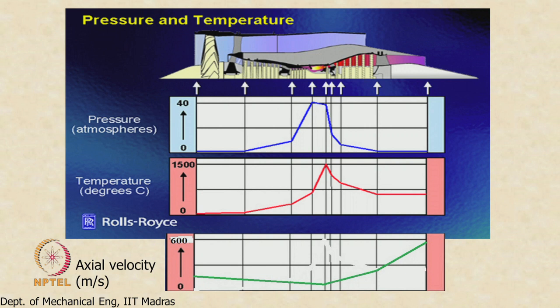Now what about the other components in this figure? You can see that the velocity here is small, so if I take the speed of sound and try to calculate the Mach number, it may seem that the Mach number is actually not very large in these parts also. However, this criterion is trying to tell me that the pressure is changing continuously, right. So any change in specific volume is going to be due to both change in pressure and change in temperature. So when I look at this too, the first criterion, I am getting a feeling that compressibility effects are significant, right.